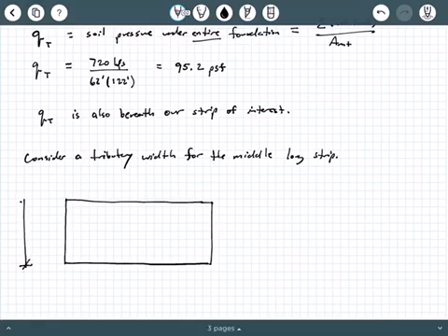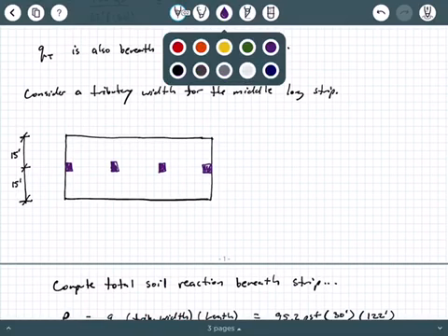Okay, so we've drawn this out, and this is the strip that we're interested in. And again, we're looking at 15 feet on both sides of that column line, okay? And again, that's based on a tributary width. So here, I'm going to try to sketch in my 4 columns. Now, when you're doing this in a more real scenario, you want to draw this to scale as best as you can. Obviously, my artwork is not the most beautiful and not the most to scale, but you want to draw this to scale, okay?